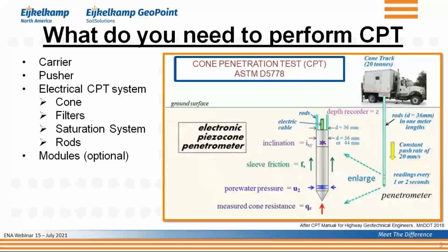And you see in the center of that illustration what you do in that cone. You measure the tip resistance, the pore water pressure, the sleeve friction, and some other stuff. And what I've told you various times, and it's very important, it's a very standardized system. Standardized in the sense that we push it into the ground with a certain speed, and the dimensions of the cone are also very much standardized.